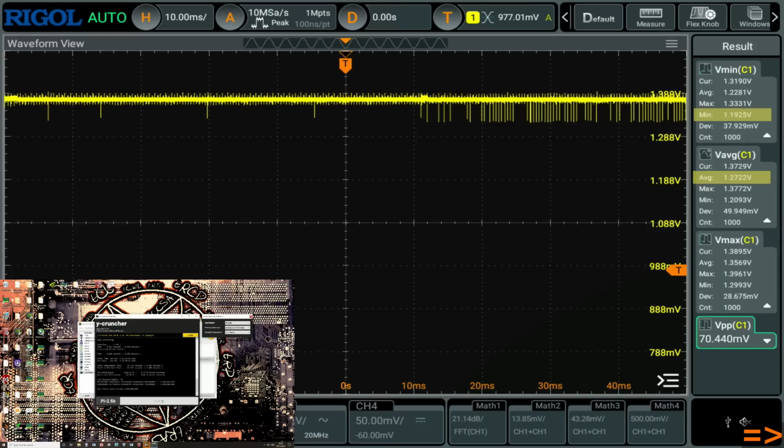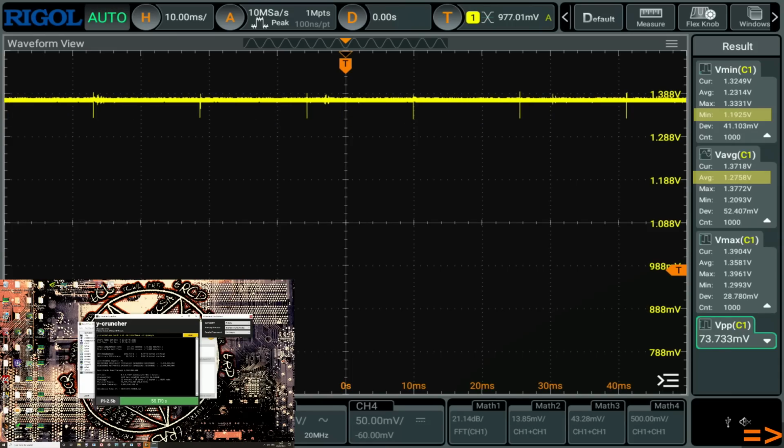The only reason you wouldn't use mode 8 is that your idle voltage goes through the roof, but with this, you can basically shift your idle voltage down. The one concern I'm wondering about is whether there's a scenario where... the saturation current, I would imagine, is relatively specific to how high you can set it for each CPU. Like, 120 amps for a 13600K with, say, the E-cores disabled, well, the 13600K maxes out at a little over, I think, 150 amps in terms of current draw. So this configuration that I'm testing right here would probably not actually work very well on a 13600K.